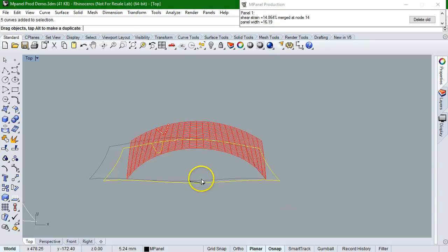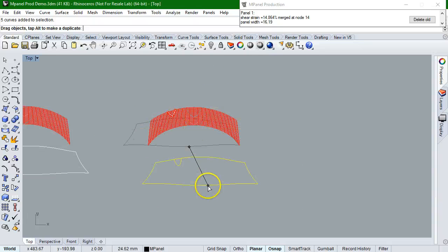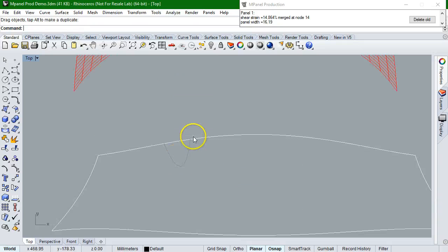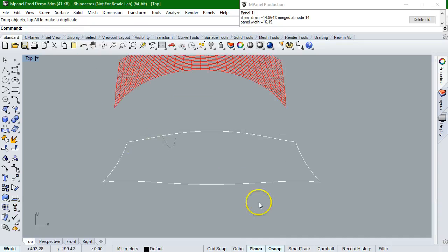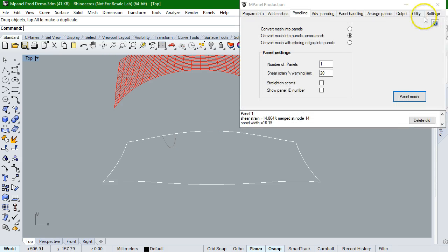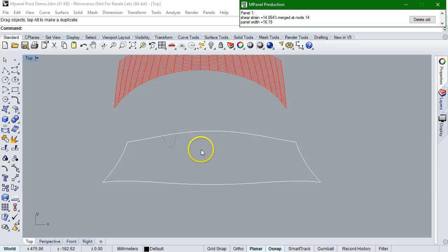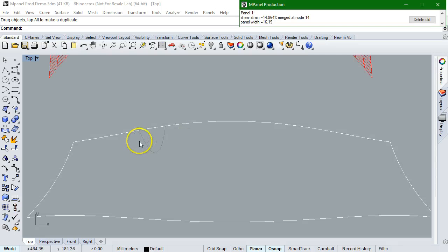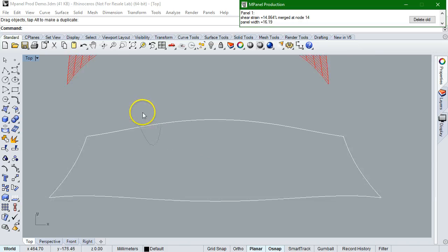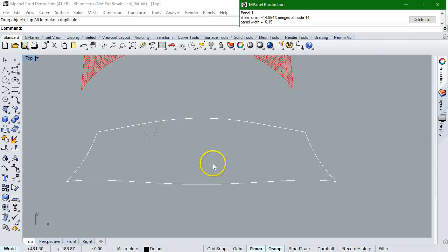when I bring the panel down here, you will see that there is a detail poly in here. I would of course go through the normal seam allowance process and so on. And if I now run the tool to produce a panel cutout, but there is no detail, there is no panel cutout polyline provided, then the tool will automatically look inside the panel to try and find any detail polys like this which could be used as a cutout.